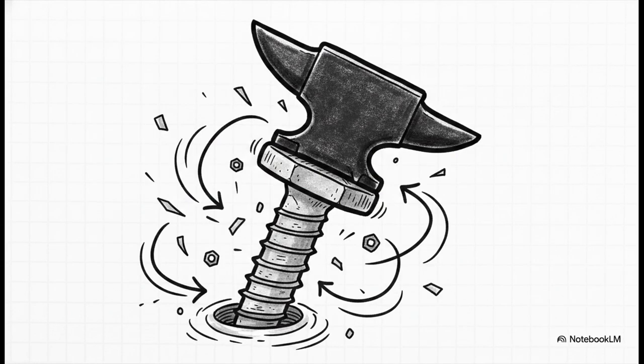On the flip side of that, we have what's known as the overhauling of screws. If phi is less than alpha, meaning the thread ramp is way too steep and the friction is too low, the screw is non-self-locking. It will literally unwind itself under the sheer weight of the load. I mean, unless you're intentionally designing a very specific kind of push drill or an automated jack, a non-self-locking fastener is basically a mechanical engineer's absolute worst nightmare.